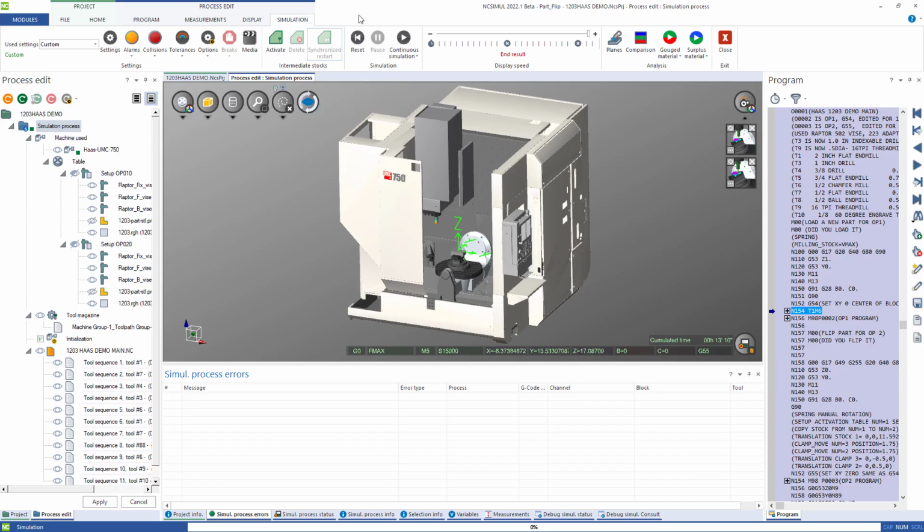And then inside here, you're really using 3 main buttons. You'll have your reset button, which puts all the material back on to the rough stock and starts the simulation over. You have the play button, which runs the simulation. And then you have a speed of simulation slider, so you can decide how fast compared to real time you want the actual simulation to run visually.